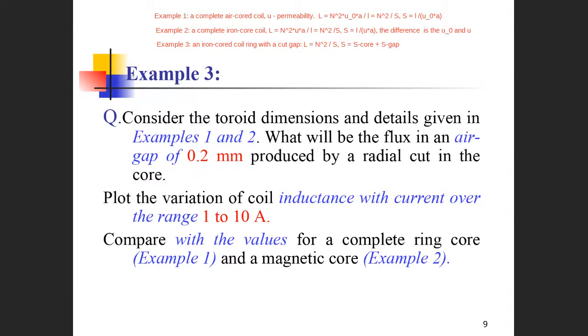So S core equals the length of the core over the permeability of the core material times its cross-section area.